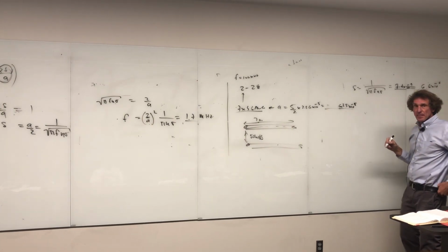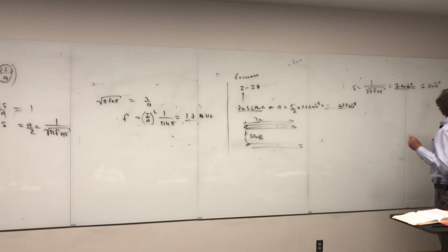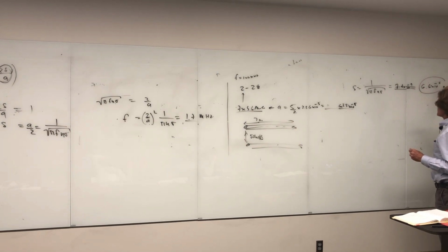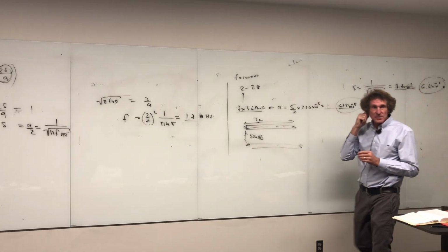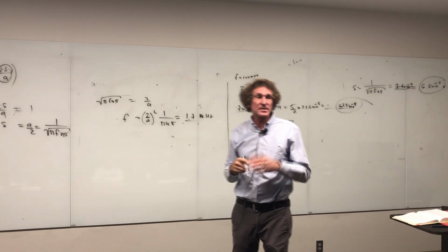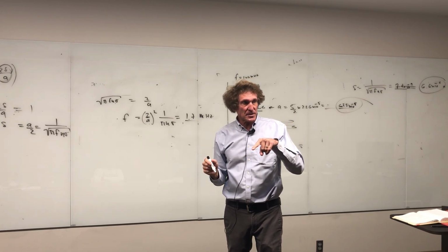Anybody confirm that? Yeah. You got that? All right. Now, that's in meters. The first thing you'll notice is what? This is substantially less than this, right? So the skin depth is much less than the radius, therefore it is a high frequency problem. All the current is hugging the surface. Does everybody follow me on this?